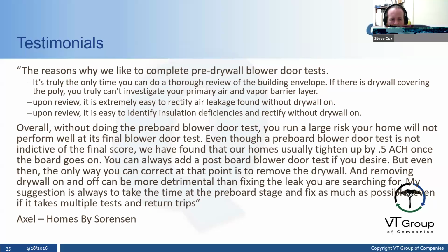Axel from Homes by Sorensen, we do his blower door test as well, his pre and posts. The reason that he likes to do pre-drywall tests is that it's truly the only time you can go through and do a thorough review of the building envelope. If there's drywall covering the poly, then you can't truly investigate your primary air and vapor barrier yourself.